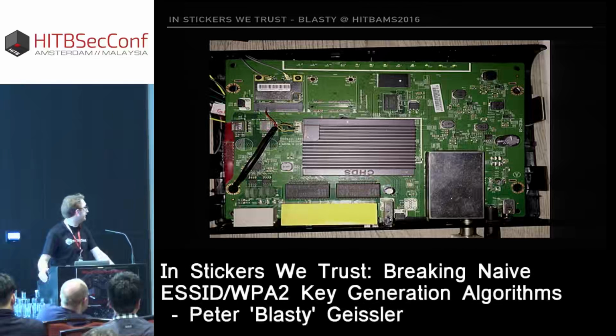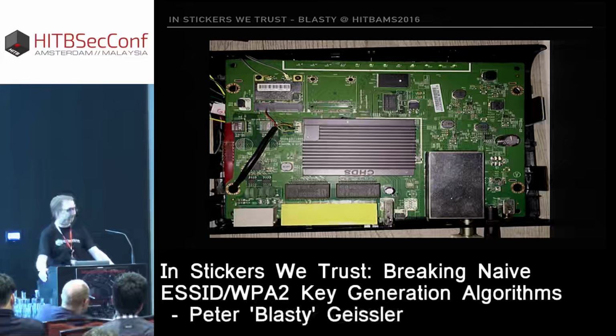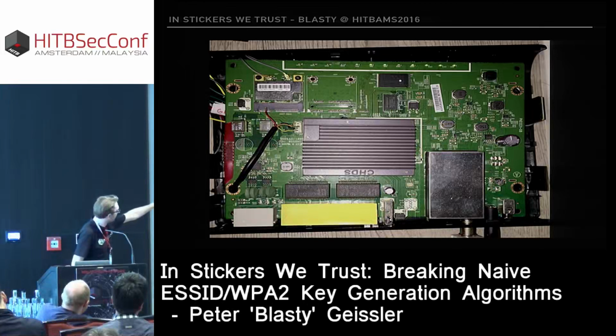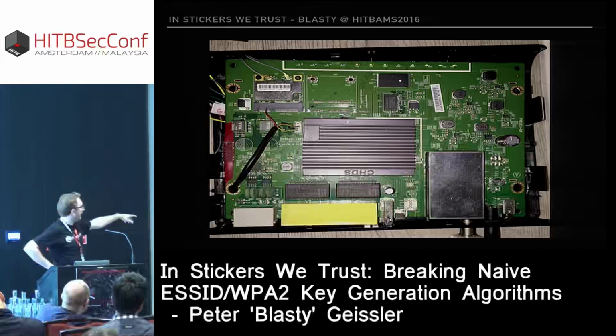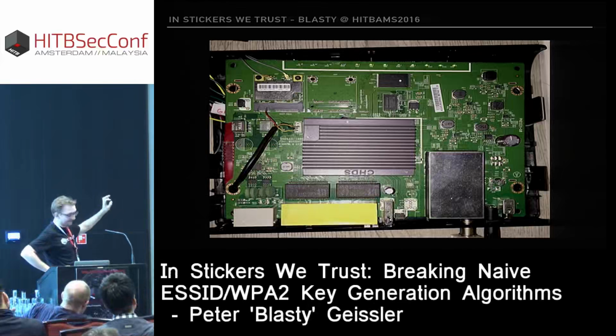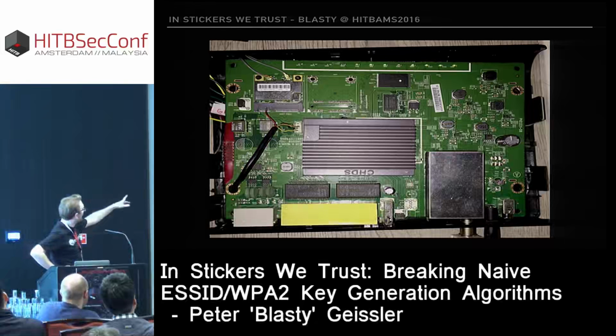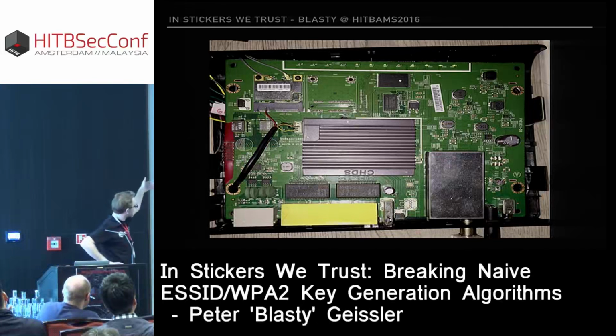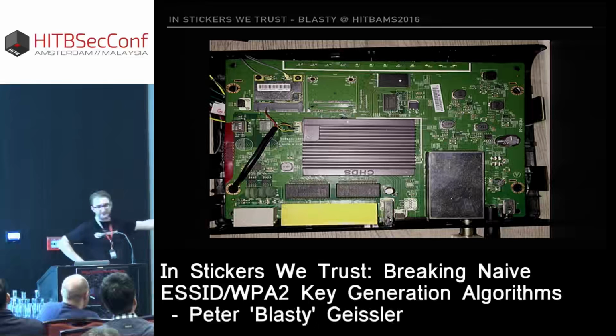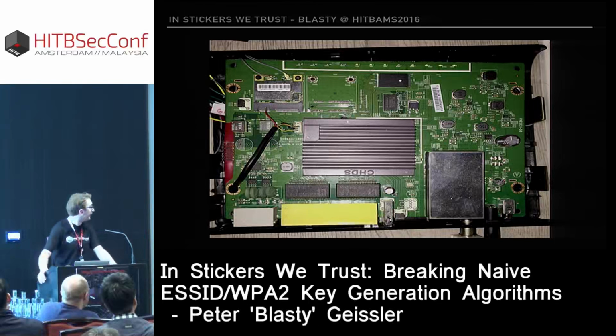If we rip off the, well, let's say the top cover of the modem board, the modem device, we can see this. This is actually not what you see. You can see already there's a cable soldered there to the board. What I found there is a debug port, a serial port. If you look on the left, it's hard to see, but there's more wires going on to the bottom side of the board. That's where I connected the SPI flash in order to dump it.